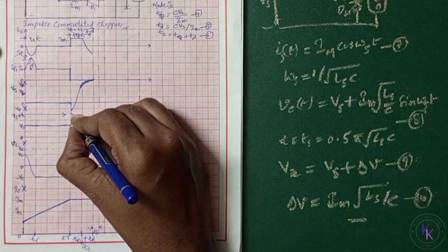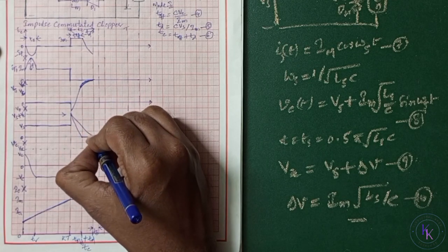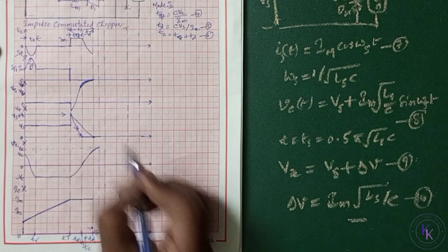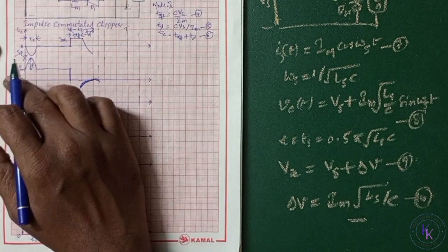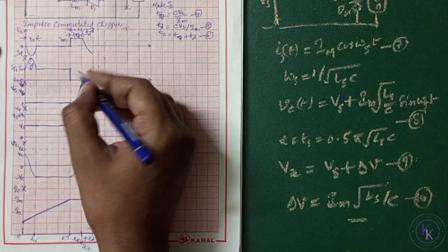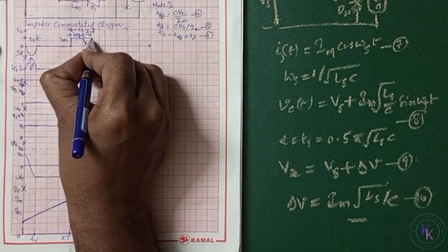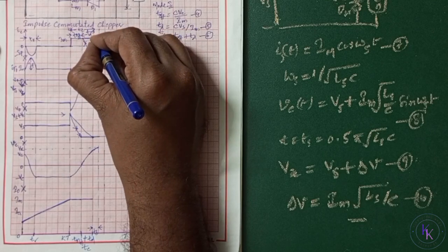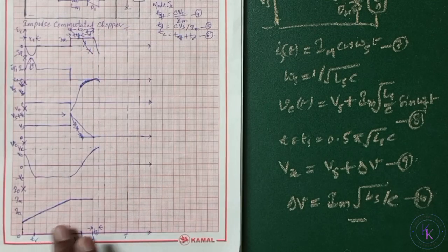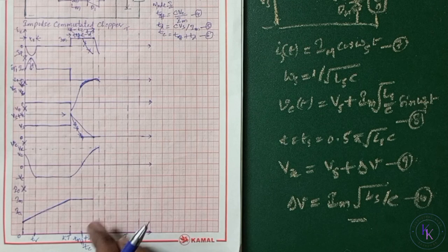By the end of commutation, the output voltage is going to reach 0. It will stay at 0 and Vt is going to rise to Vx. It1 will be 0 and Ic will be at Im until Tc, the commutation time. After the commutation time, it starts decreasing to a minimum value. The output voltage is going to decay in this time.